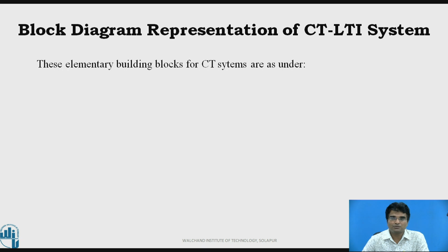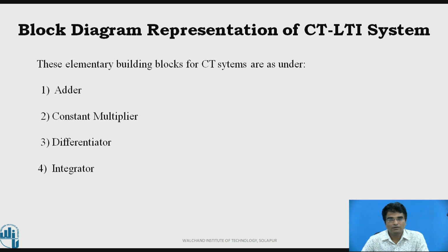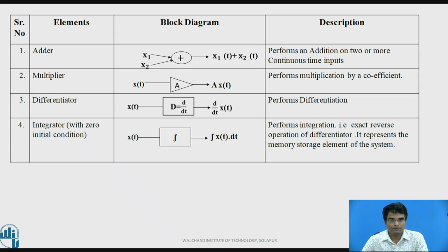Block diagram representations of continuous time LTI system. These elementary building blocks for continuous time systems are as under. First one, adder, constant multiplier, differentiator, integrator. Here adder: x1 and x2 are given as input to the summation, and we get output x1 of t plus x2 of t.